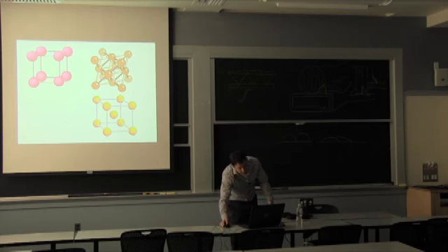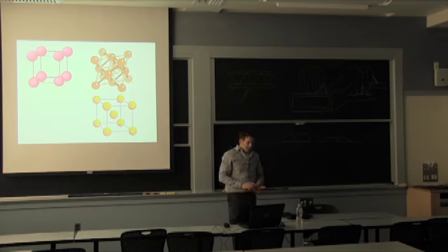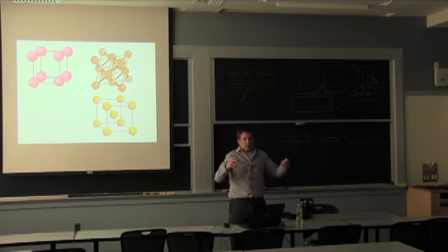And the reason it stretches is to make room for the carbon. And this whole transformation essentially happens without having to get all the carbon together in the form of cementite. You make your network able to fill in and accommodate the carbon.